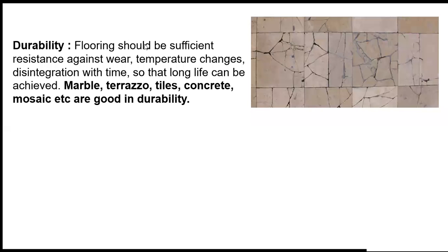So durability: floor should have sufficient resistance against wear. That means if you are pushing some equipment on the floor, it does not mean that due to its pressure, it should wear. No. Then if there are temperature changes, your material should be such that it can bear the temperature changes. Because in India, the day temperature normally varies from 20 degrees to 45 degrees. So there is a lot of variation. There will be a lot of temperature stresses. So your material should be such that it can bear the temperature changes also.